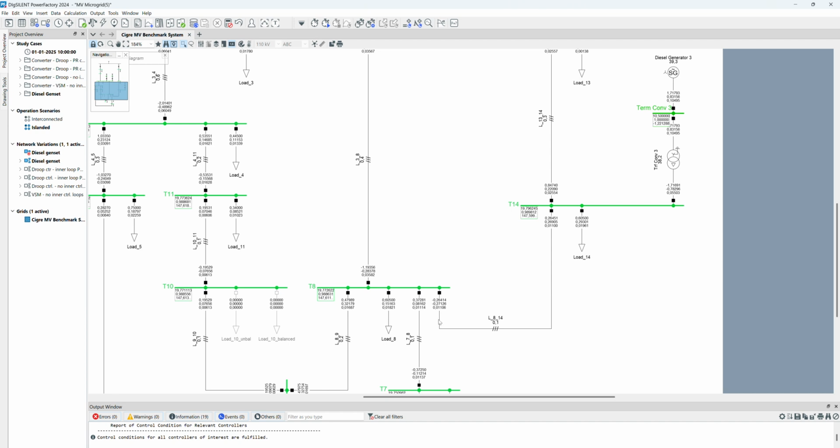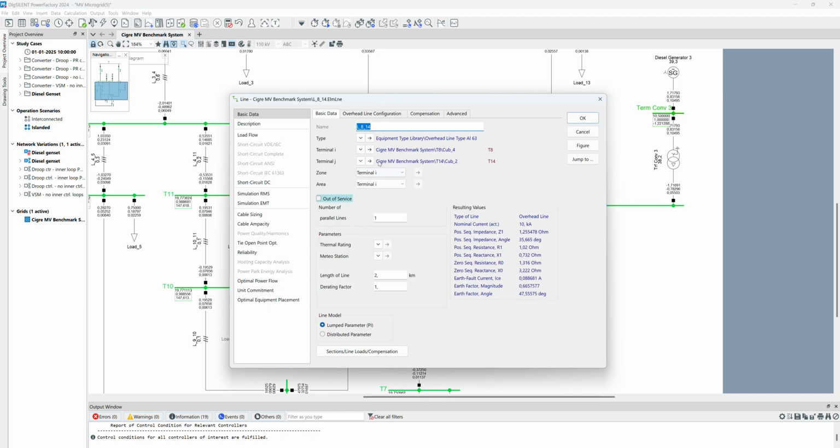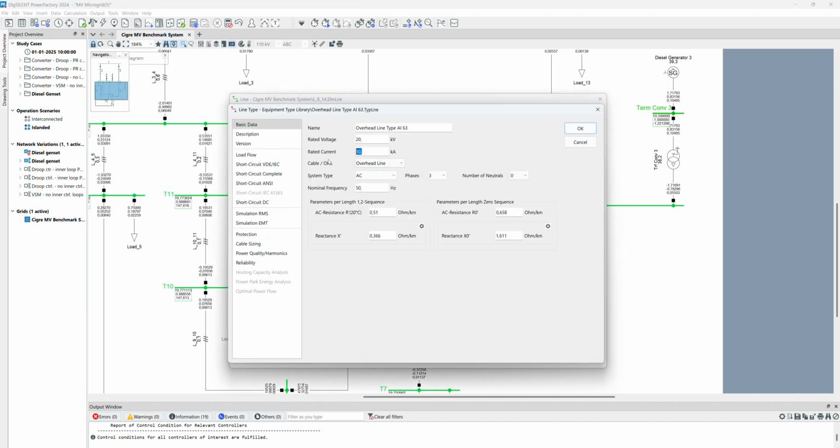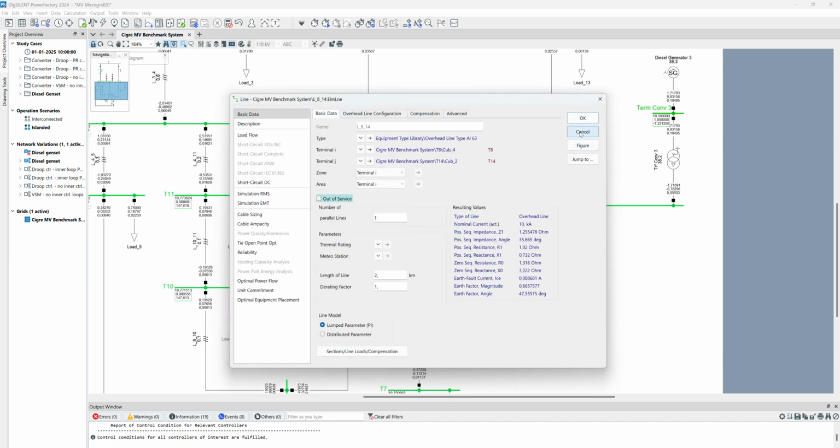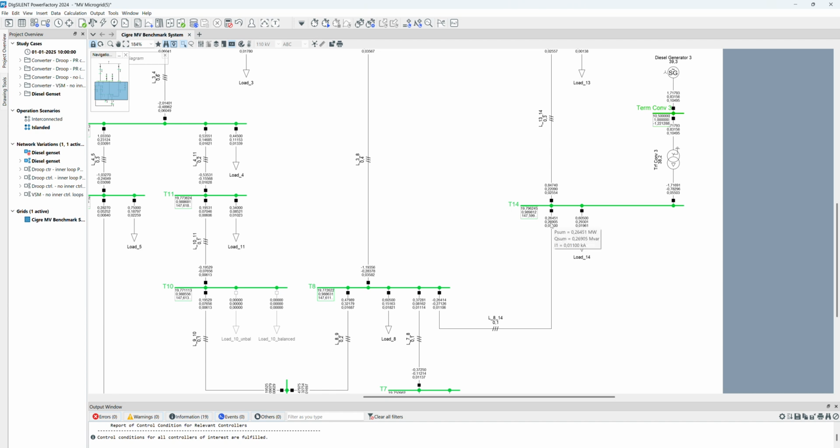If we assume that, because the loading is 0.1%, we can assume that the 11 amp is full load, for example, now. If we want to find the rating, 10 kilo amp is much higher than the short circuit level in this example. So we assume that 11 amp is the value of the full load. So we add 25% on that one, so it will be around 15 or 16 amp.